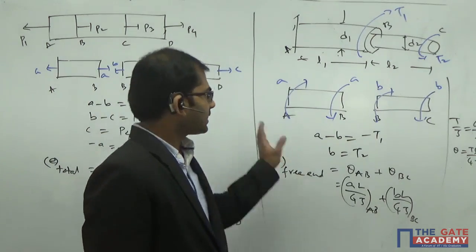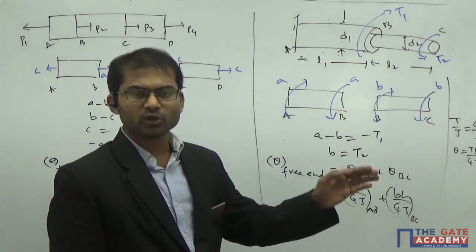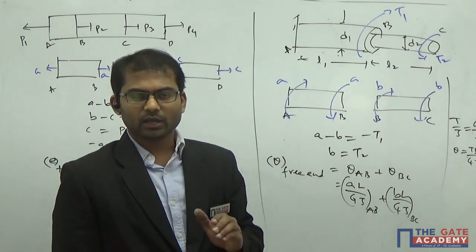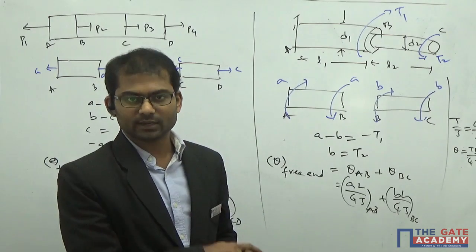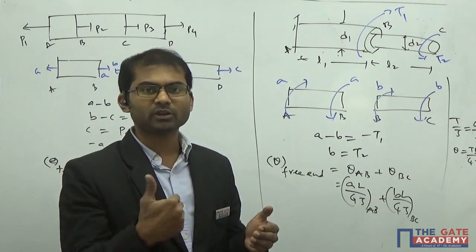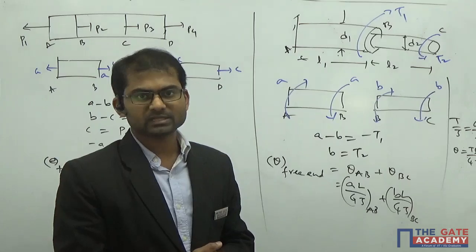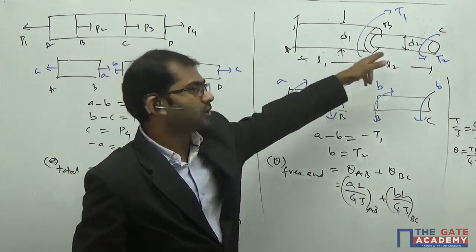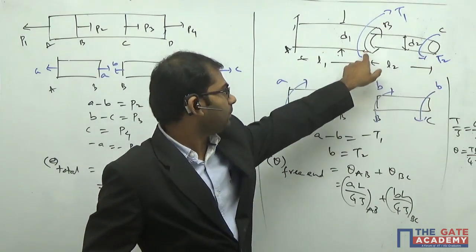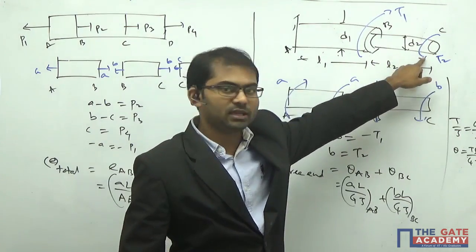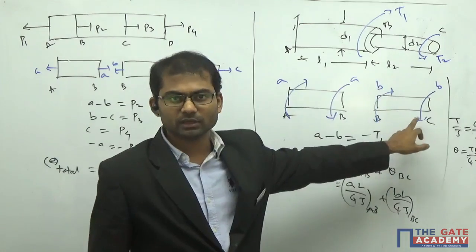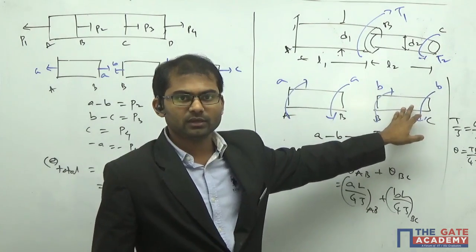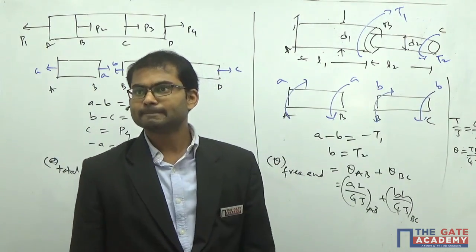Dear Darwin guys, in this case torque will not remain the same. I'm going to show you another series arrangement where you're going to observe a different thing. This is the first section of shafts in series here, and another section is also there. After completing that part, you'll come to know. So torque will not be the same in all these cases. External torque is applied to section B and section C, so that will give rise to different torque at section AB, different from BC. Understand? Clear?